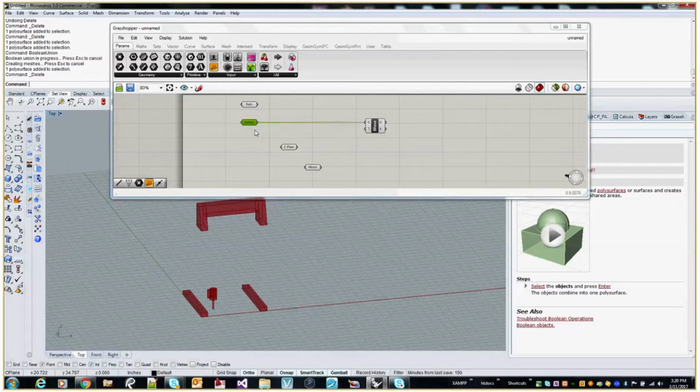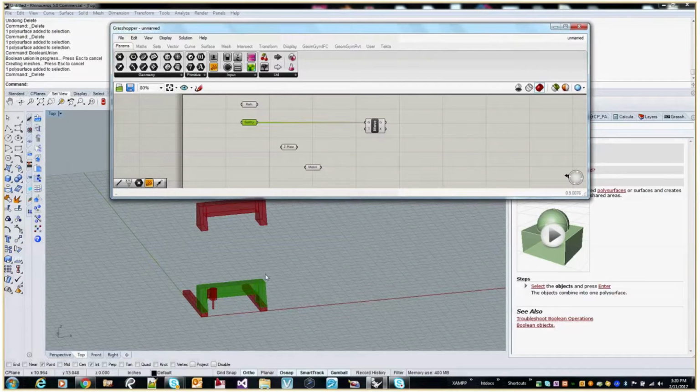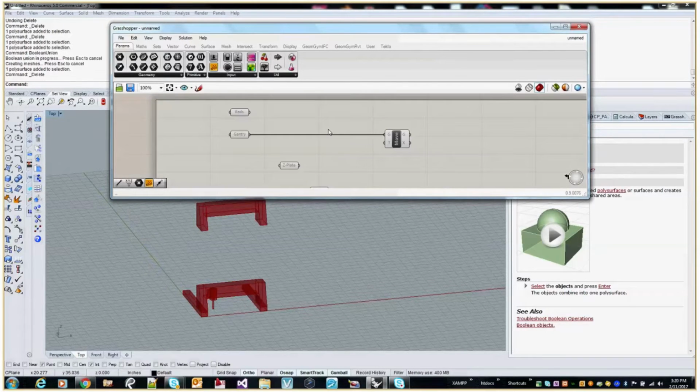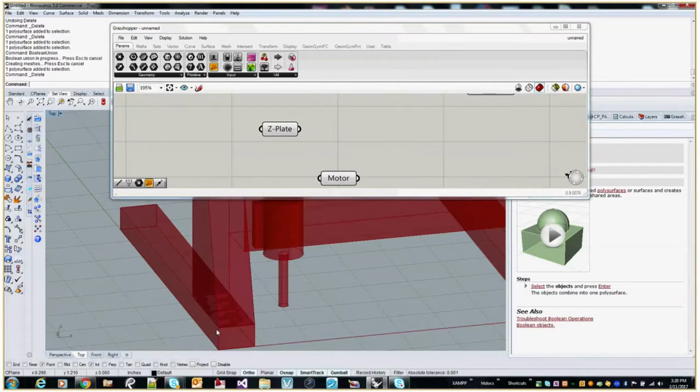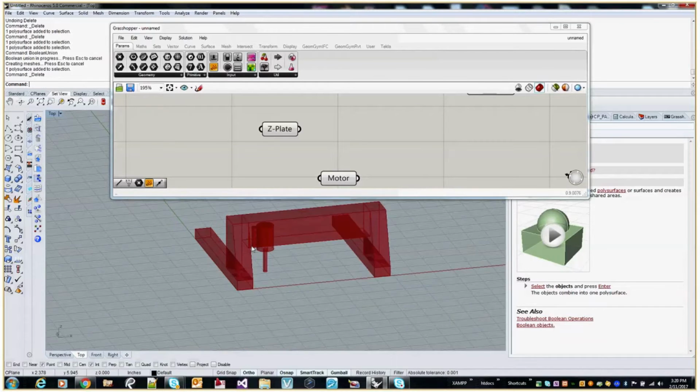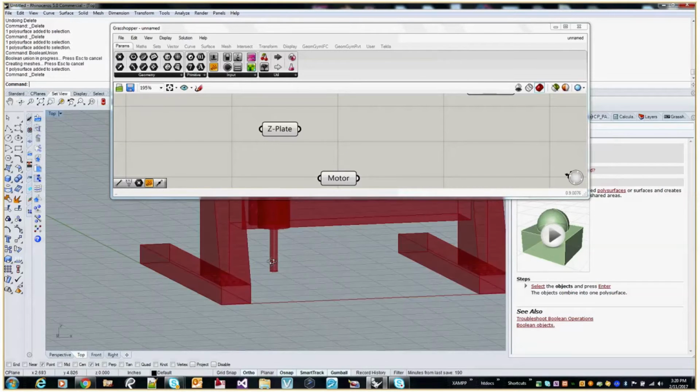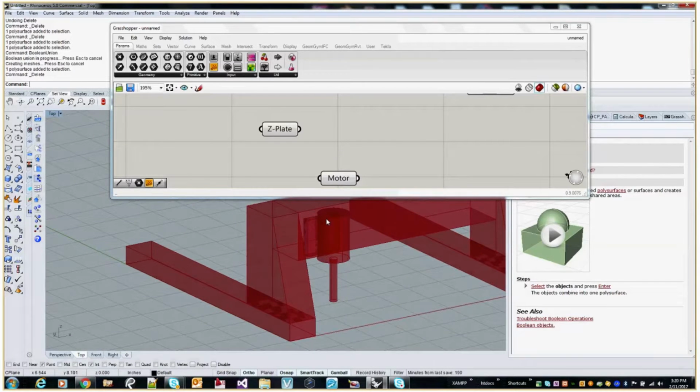That's okay. I'm going to turn back on the preview so we see where the original's at this point. But I know that our limits are basically where I've placed these. I try to draw the limits of where this is at its lowest y value possible. So I'm going to call that machine 0 for the y. And I'm going to say the same thing for the x, that's as far left. I'm going to call that x0. And in our case here, I'm going to call that z0, machine z0.